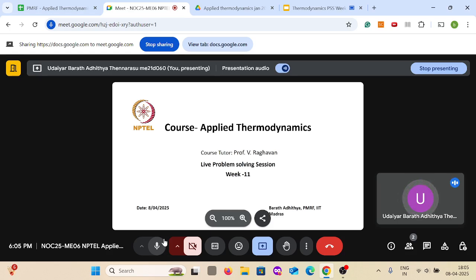So where do you come across this? So if you want to measure temperature or pressure, so if you want to measure temperature, there is a flow happening. You put your thermometer or the temperature measurement device, and the flow comes and hits it, and at the point of contact with this, the flow is happening, but near the sensor, the fluid is at rest.